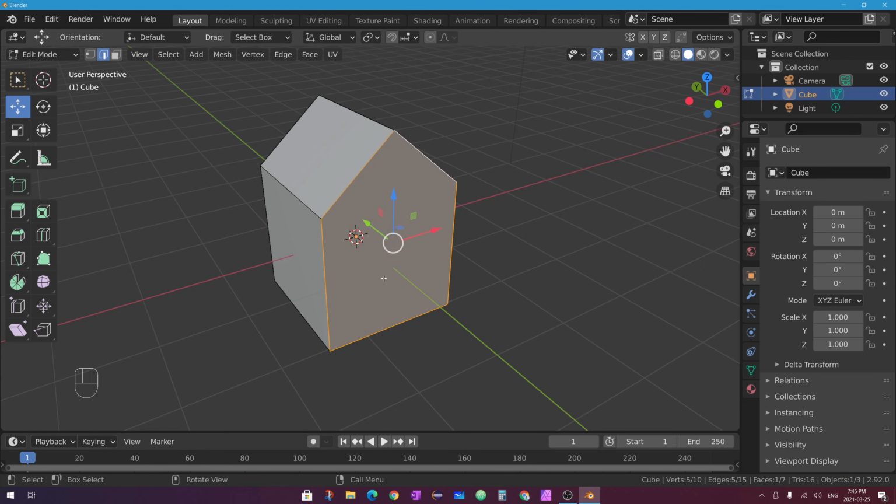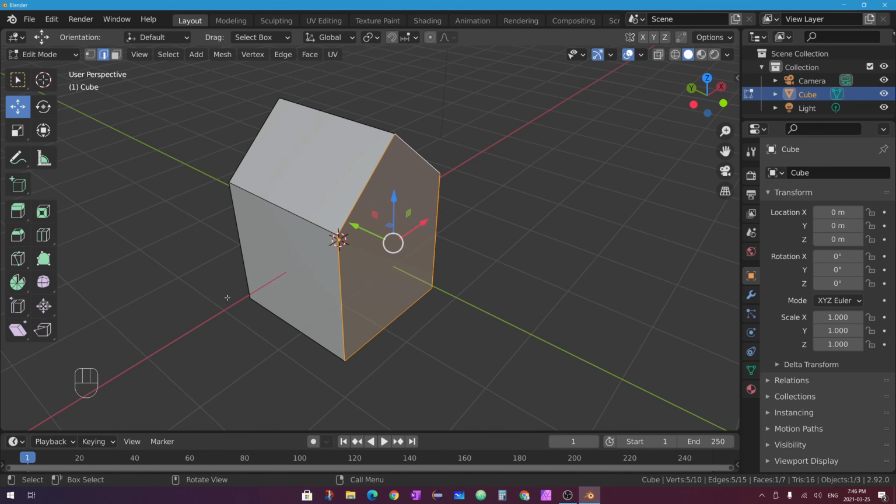Now, N-Gons are okay sometimes, but ideally you try to avoid them. N-Gons can cause problems with future tools we'll talk about in this video. N-Gons can also cause problems when you're trying to smooth out an object or animate an object. N-Gons are just not a very nice way of maintaining a nice topology on your mesh.